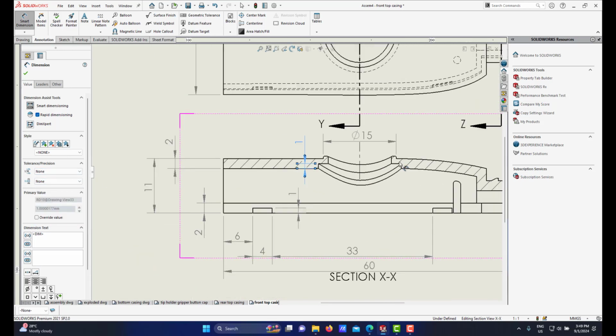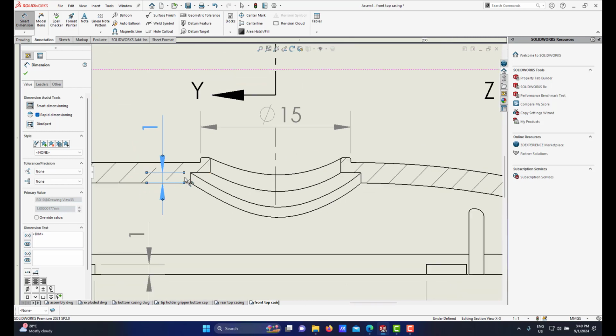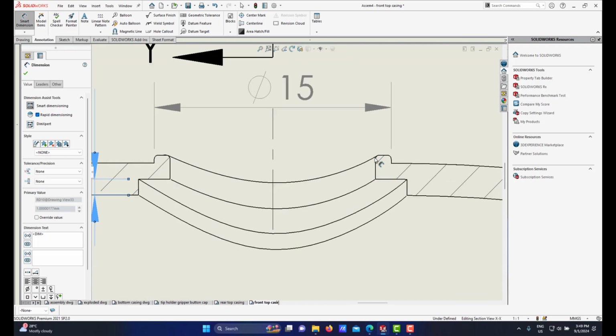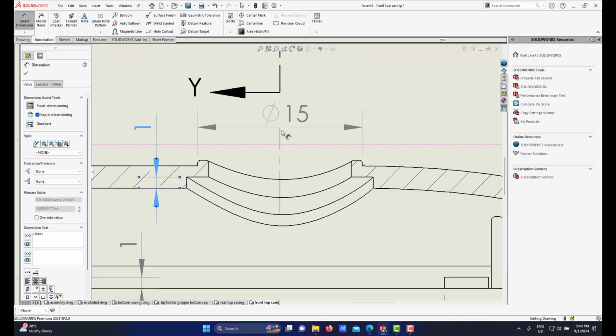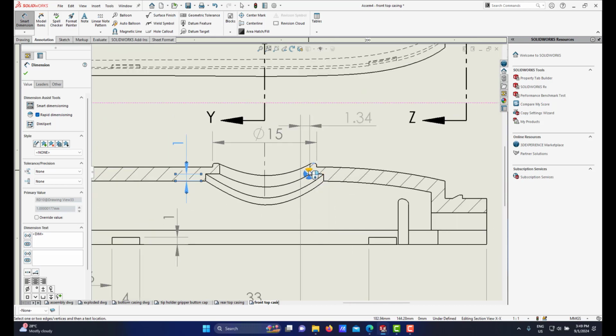All right, so I need to give the height of this level since this is already 1 and we know the thickness is 2, but we have a balance here. From here to here, we need to show also the dimension from this line to this line. If I cannot go for line, I can go for endpoint, like this, vertical distance of it.